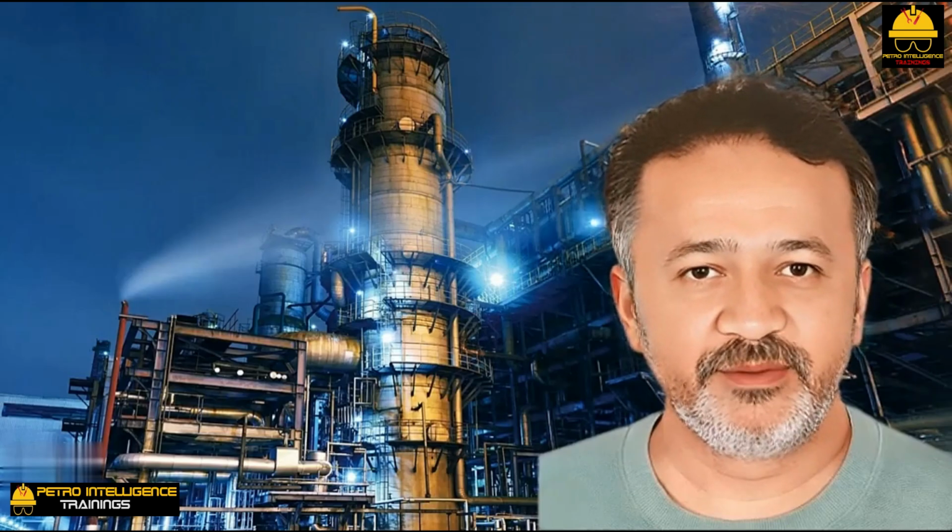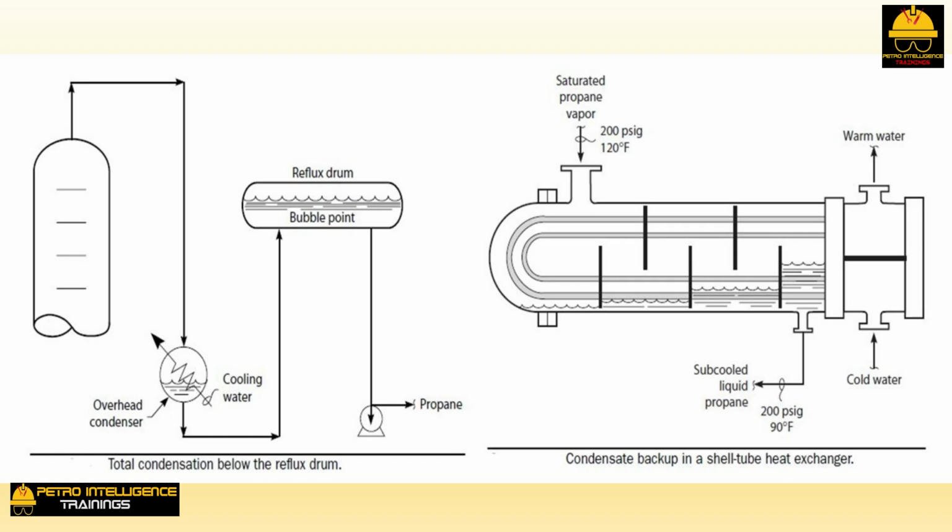Effect of condensate backup. When the condensate level in an exchanger increases, the area of the condenser devoted to subcooling the condensate increases. But the area of the exchanger available for condensing decreases. That is bad. When the area of the exchanger available for condensing is reduced, the ease of condensation is also decreased. Depending on the circumstances, one of two unfavorable things will now happen.